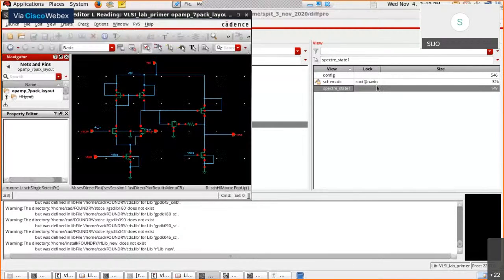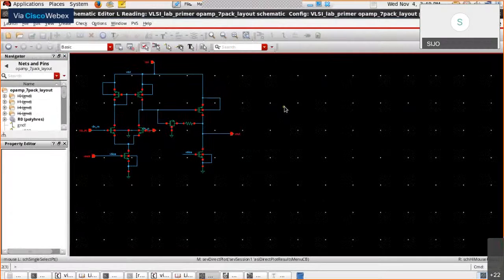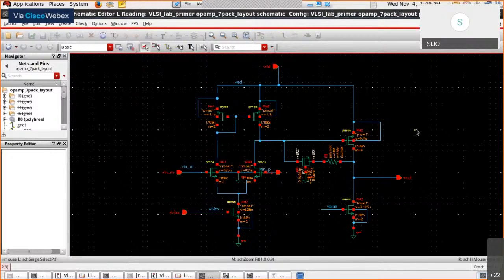I hope you remember, we designed it for a power consumption of 50 microwatts, with a drain current for the first stage of 12.5 microamps through each input device. Then you have a second stage, basically a two-stage op amp, and the final stage is again a class A stage, with a PMOS as the input device, with a drain current consumption of 125 microamps. We designed it for a gain greater than 60 dB, looking for maximum unity gain bandwidth, so we chose minimum L.